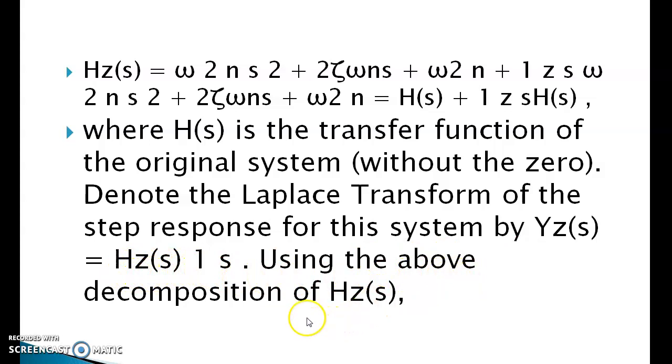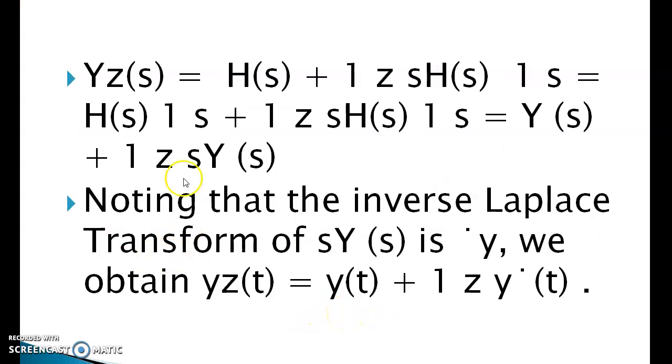Using the above decomposition of Hz(s), Yz(s) = H(s)(1/s) + (1/z)sH(s)(1/s) = Y(s) + (1/z)sY(s).